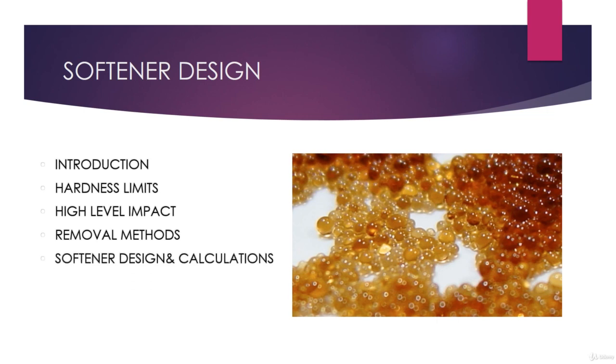detailing each stage of the design of the softener system and its regeneration system. Calculations determine the amount of resin required, instructions for installing the resin, and specifications for the vessel, and calculating the dimensions of the vessel, the diameter and the height. Calculations for determining the required amount of regeneration material, stages of regeneration process, and its accessories. Finally, the softener control head design and the specifications of regeneration brine tank.